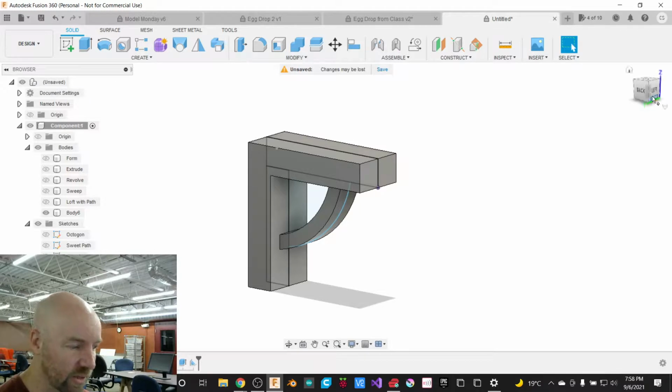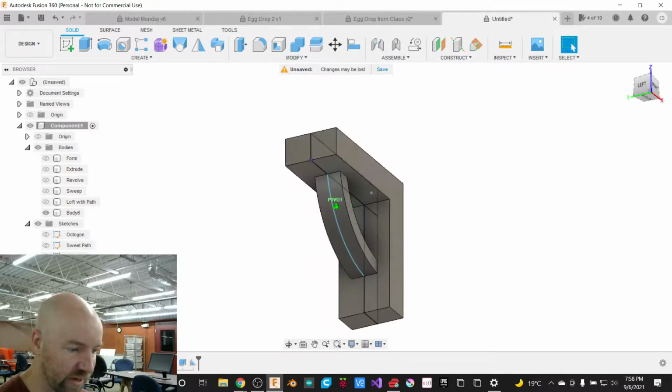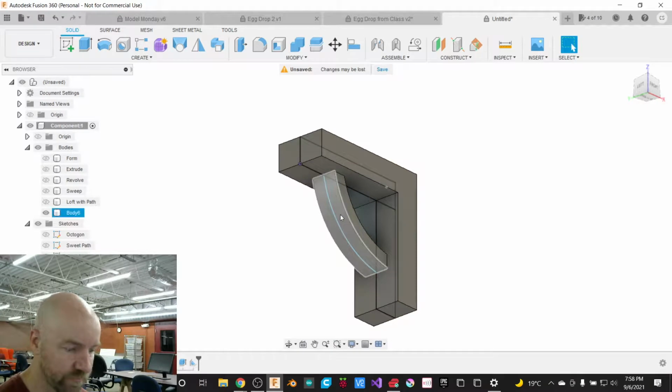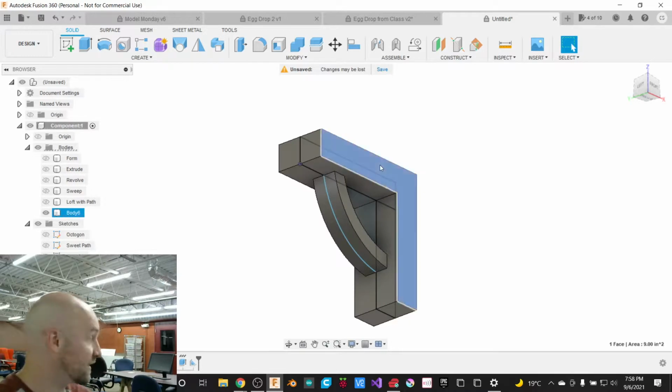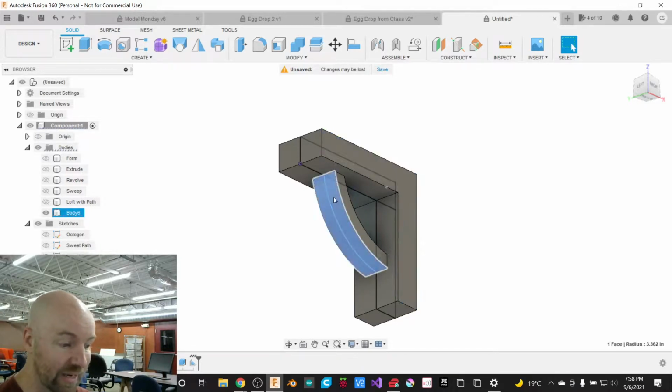Here we go. Let's do this. We've got a curved shape here. If we wanted to put lettering on this flat side, super easy, right? We could do that with an extrusion. Nothing to write home about. If you want to write lettering on a curved shape, then this emboss feature is super handy.